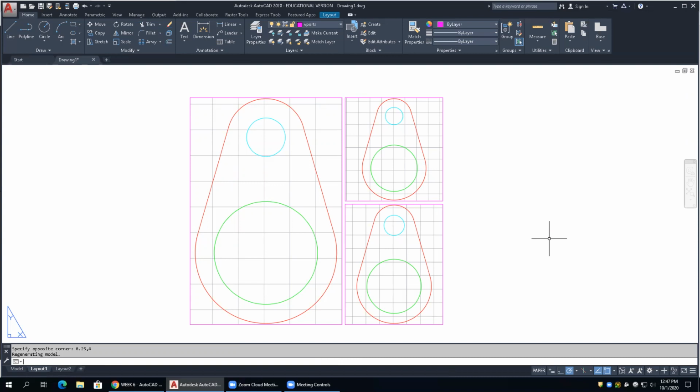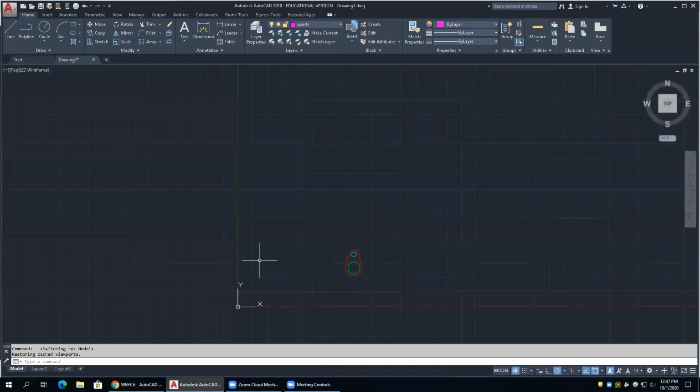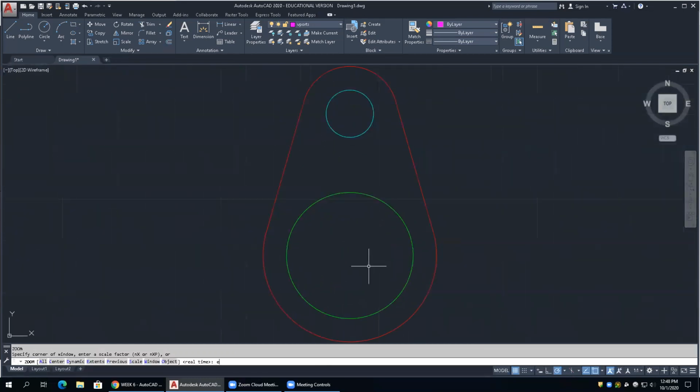So let's do this real quick. Click on your model tab. You should just see your model. See any viewports? Viewports don't exist, do they? Because they're in a different dimension. So what happens in the model stays in the model. What happens in paper stays in paper. And they can't cross. All right? They can't cross. Now, there is a way to do what's called change space. So you can go into model space and change the space into paper space and vice versa.